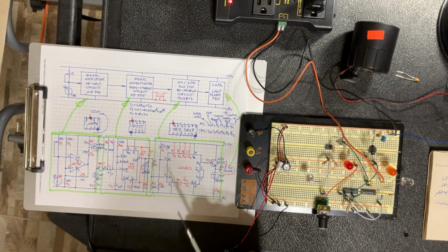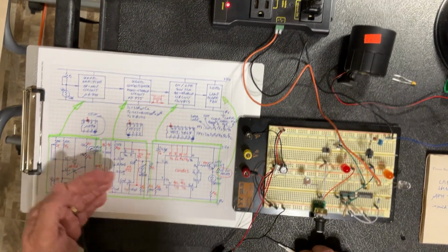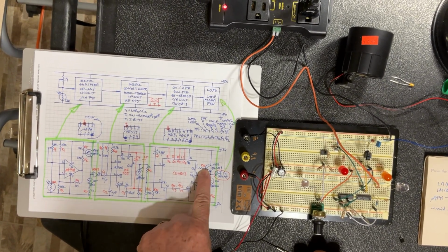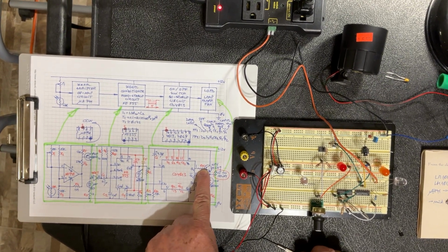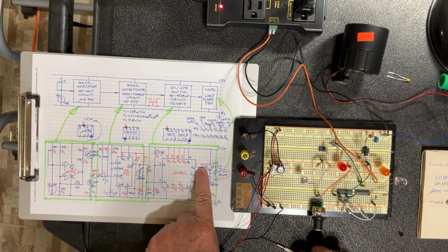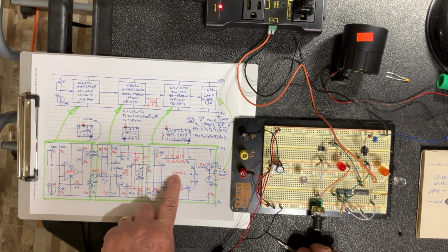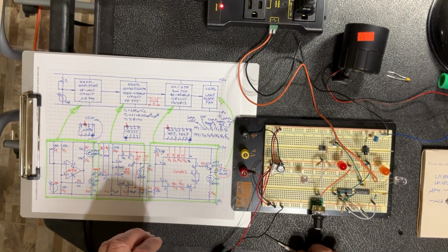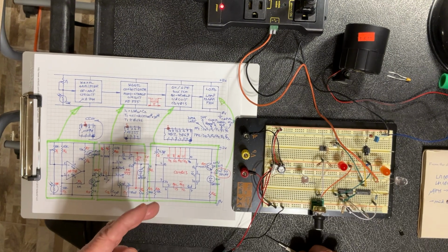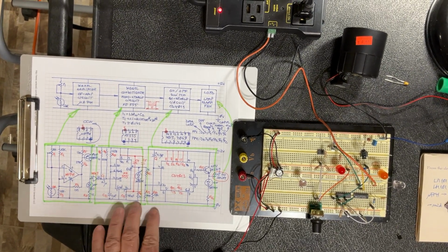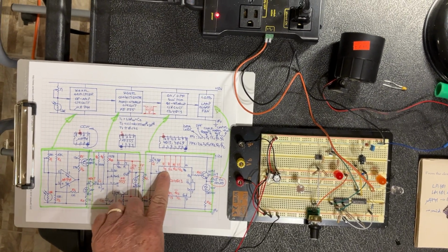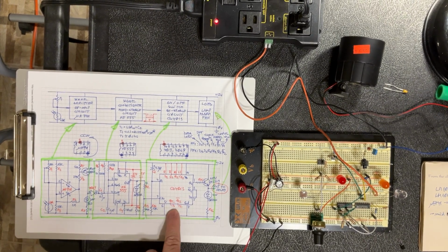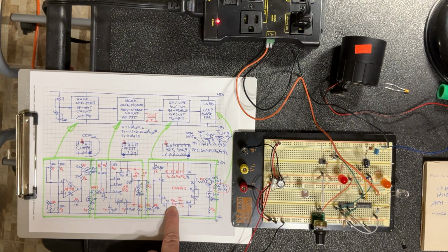What is the next stage about? The next stage is: anytime it receives a signal from the 555, if it was off, the output goes on. If it was on, next time it receives a signal, it goes back off. And this little trick is because the package 4013 is a dual flip-flop. What is the dual flip-flop? It has 2 flip-flop circuits inside, but we only need to use one. And for that reason, the pins regarding the second flip-flop I put in red. The outputs, you do nothing to them, you don't touch them, pins 12 and 13.